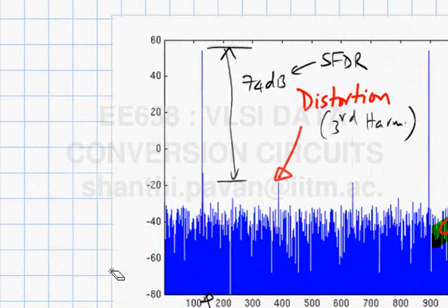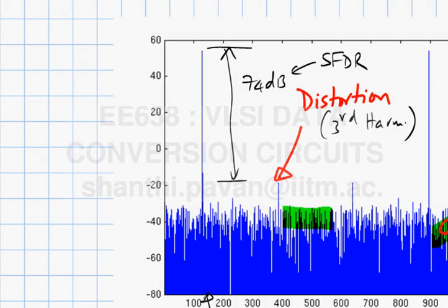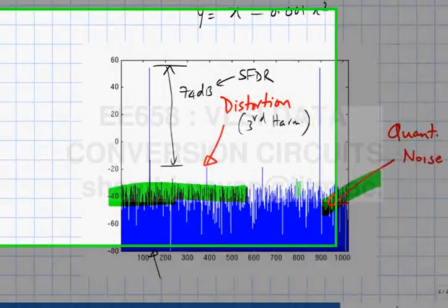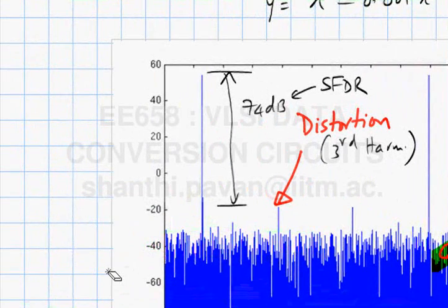But one other thing you can observe from here is that if the number of levels in the converter is very, very large, the spectrum kind of looks, the peaks kind of all, so this is certainly not a justification, but this is just to show you that the white assumption may not be all that bad in fact. And as it turns out, it's a very good assumption.